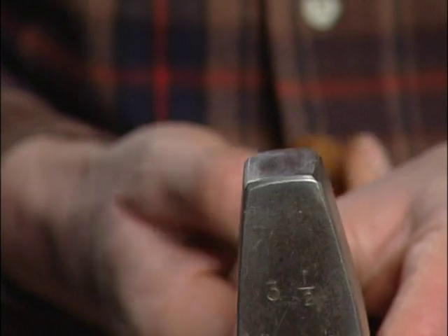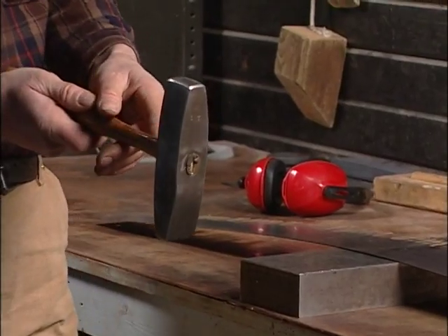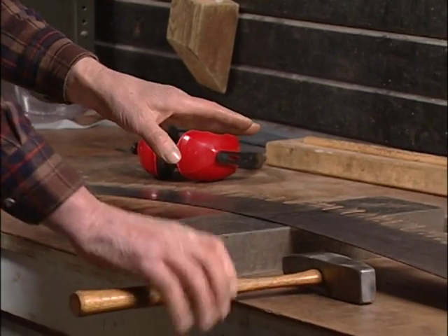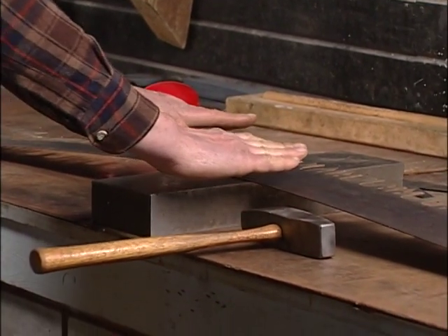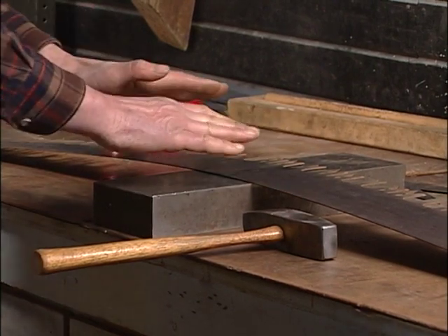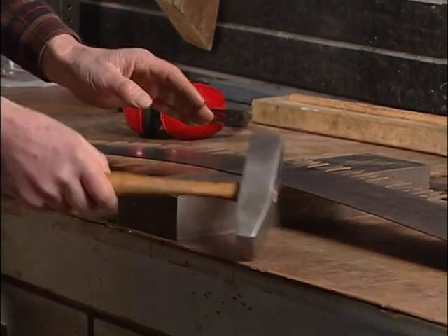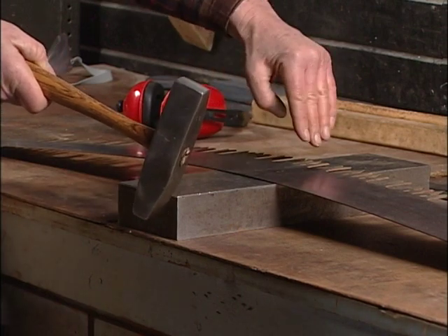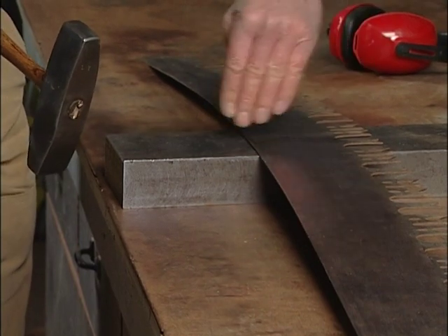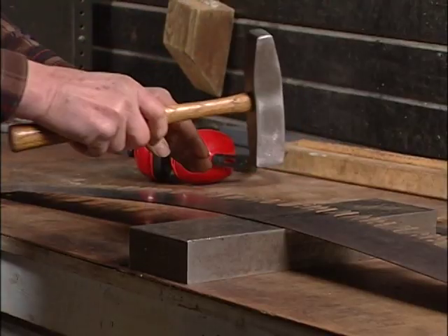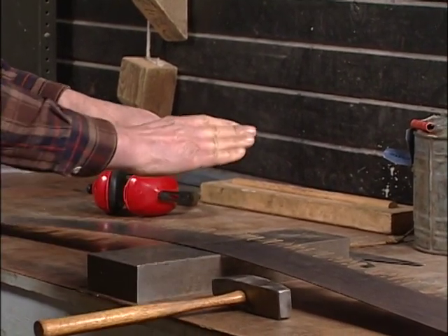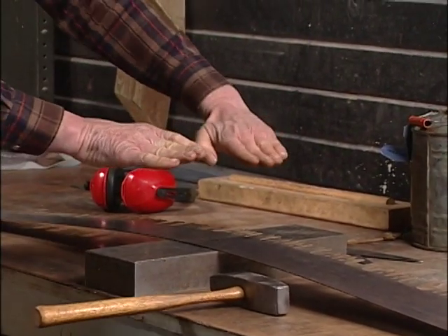The reason that's important is you need to bend the kink reverse to what it actually currently is. In order to do that, you need to have the axis of the short radius parallel to the axis of the kink, which means that when you hammer on that, it'll bend the metal this way, but not this way.